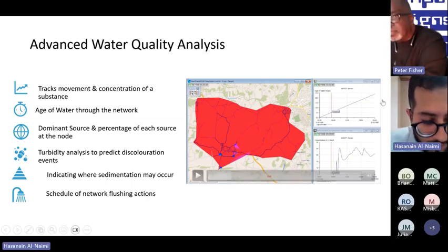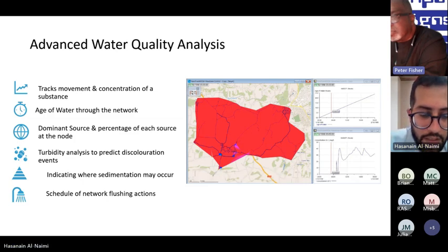On the pumping line, if you have a new pipeline, as it ages, the internal roughness of the pipeline increases and requires more energy. The frictional losses increase because of that increased roughness. And the pressure head needed to force water along the pipeline increases as the pipe ages.